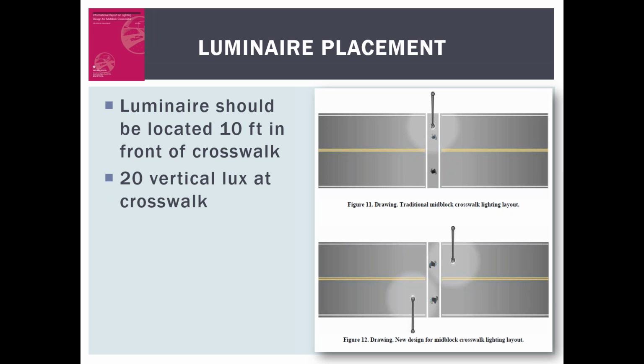Most street light systems that I know of, I don't know of any that are on a time of day basis. I know they're typically on, and there may be some, I just don't know of them. They're either individual photocells or a single photocell that may control a number of streetlights, so that it's based on the actual lighting levels that are out there. If you have a bad storm in the middle of the day, it might cause the streetlights to come on during the middle of the day to provide the extra lighting, where there's a lot of clouds,